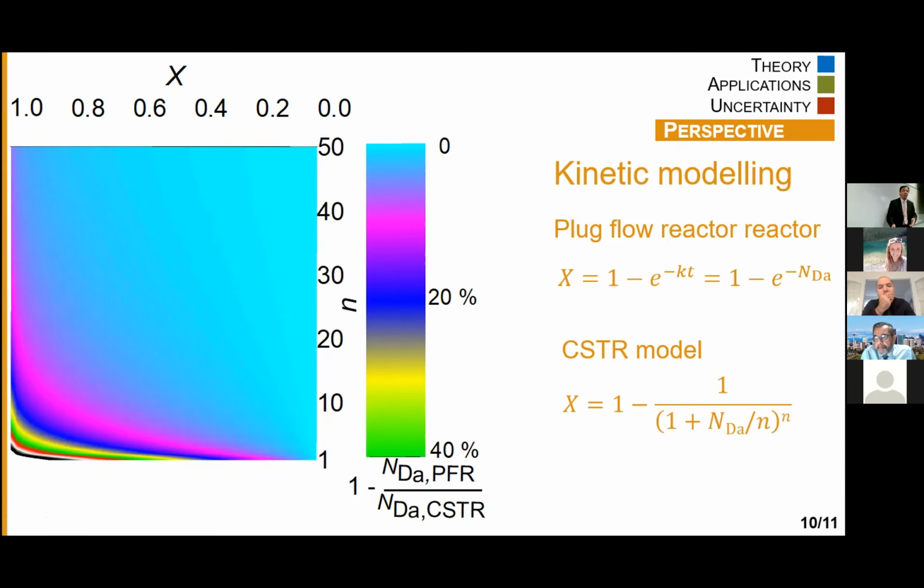So when you're operating a fluidized bed for kinetics, you've got to make sure you're operating at around 60% maximum conversion, maybe even 80%. If you've got 16 as your number of CSTRs in series, you can operate up to 60 or 70% and assume that it is back mixed, which is kind of interesting.